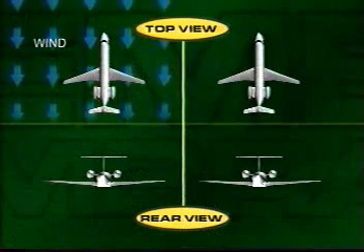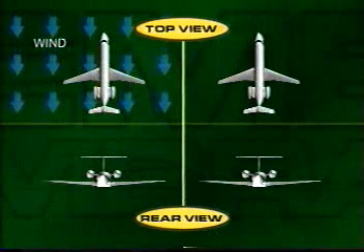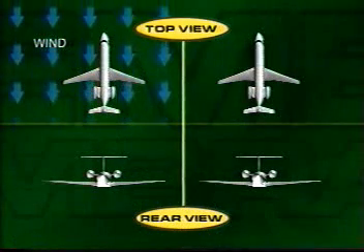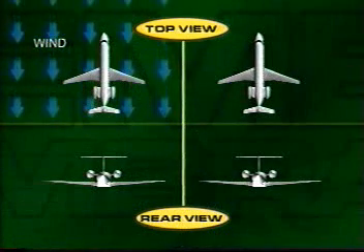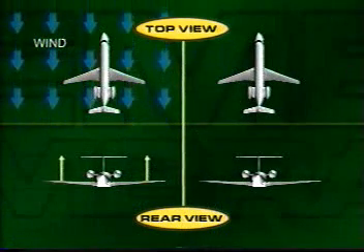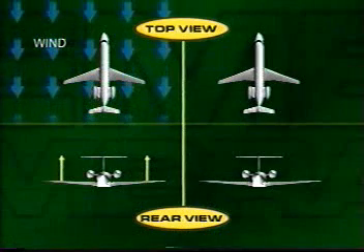Wing sweep also produces a rolling moment due to side slip, caused by the change in relative sweep of the left and right wings. Due to wings being swept in a high-speed jet, the effect is normally stronger than in turboprop aircraft. See how it works.